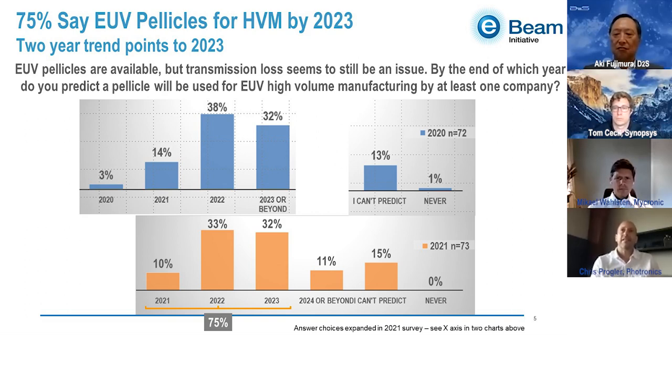The second thing is, I think there's a lot of work being done to minimize the effect of fall-on particles on the mask. For example, we call it a sticky mask. Basically, it circulates through an EUV scanner and picks up particles inside the tool. I can't really say, but let's just say our sales of that particular product have gone up dramatically.